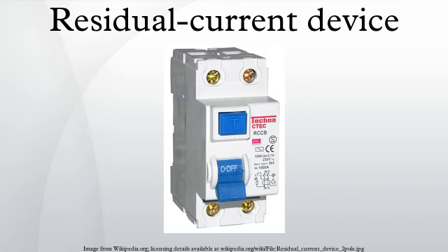By contrast, conventional circuit breakers or fuses only break the circuit when the total current is excessive. A small leakage current, such as through a person, can be a very serious fault, but would probably not increase the total current enough for a fuse or circuit breaker to break the circuit, and certainly not to do so fast enough to save a life.